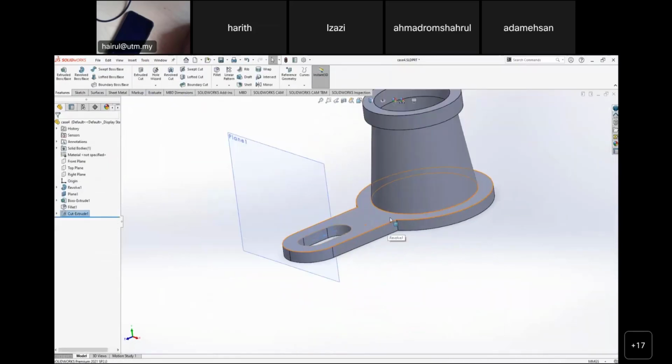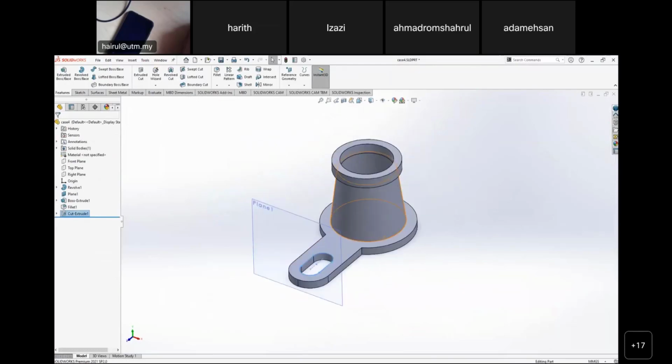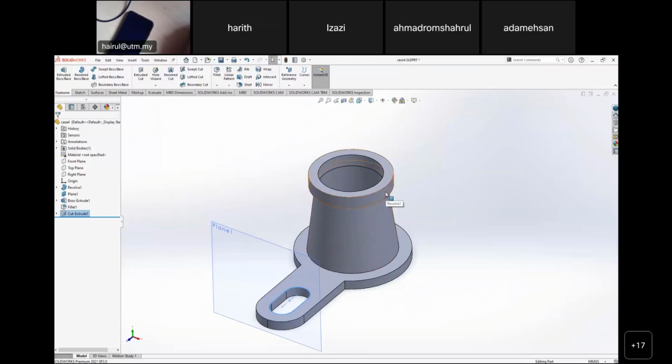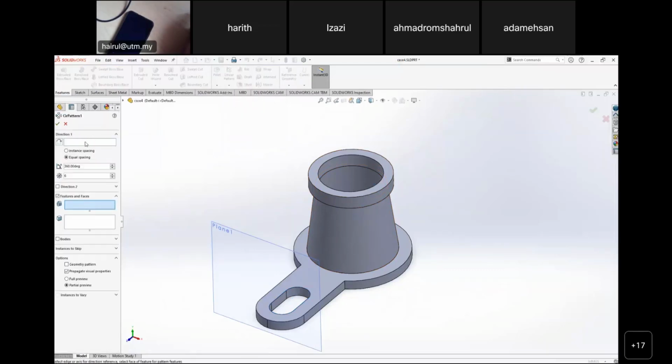So you have this one. Then next one, circular. This is how we call circular pattern again. Number of 3 for 360 degrees. Then we go for features, we go for linear pattern, we go for circular pattern. Be careful. First thing is direction. What is your guideline to circular motion, circular path? So we can select it. I can select these edges. I can select bottom edges. I can select even this, as long as I have edges of a full circle. Now angle of course 360 degrees, but we have number 3.